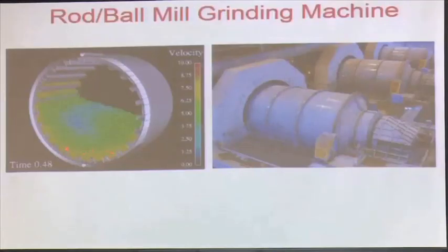It is like your grinding mill. You have a tubular structure where you put your material. Along with that, we also pour some steel balls which are much harder than the material to be broken, and then we rotate that tubular machine, which is called the tumbling mill.